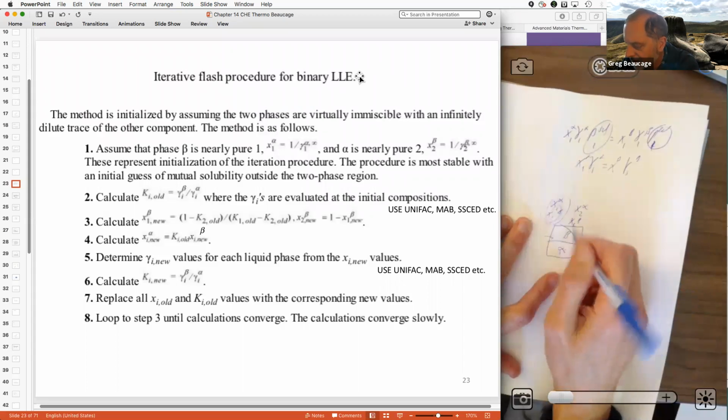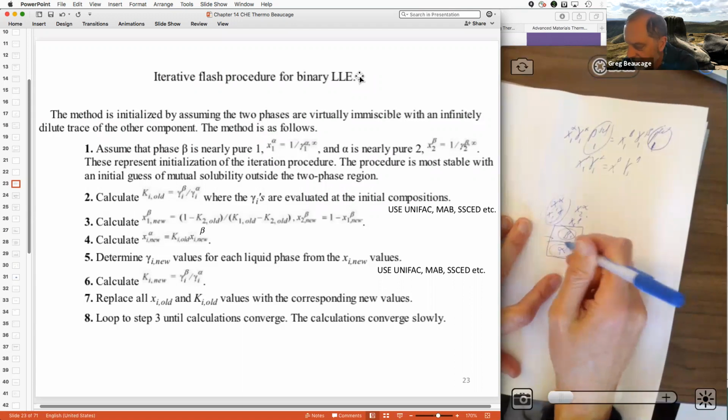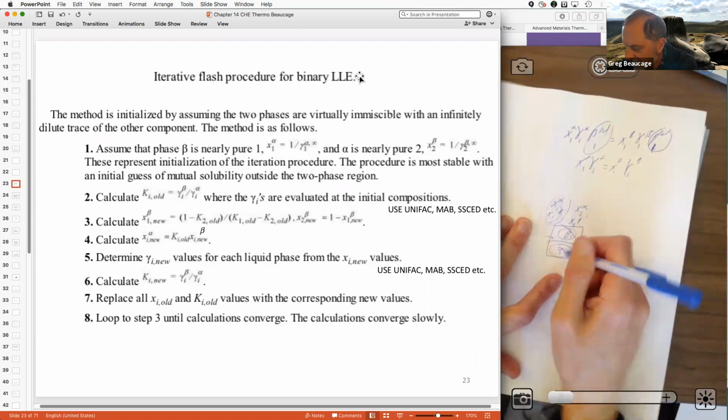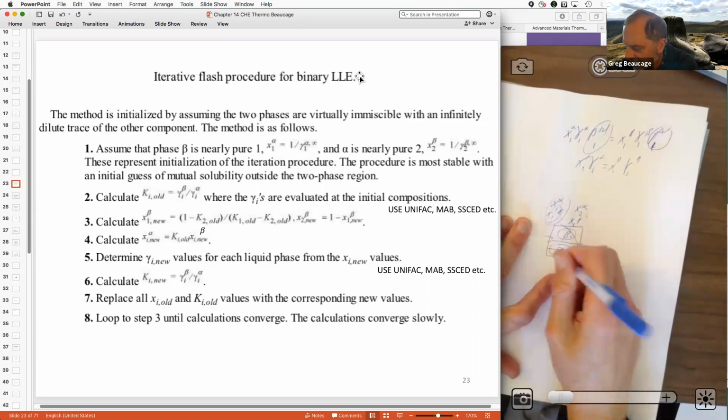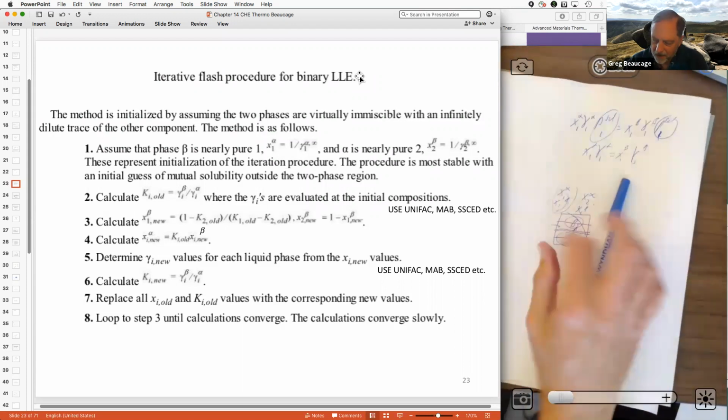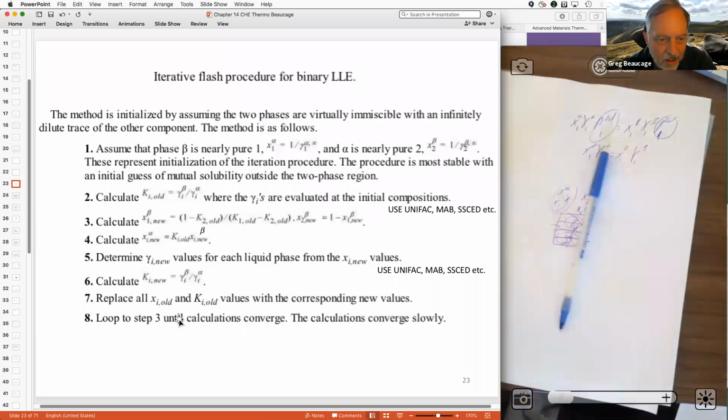You sum those two, you get the mass of alpha, you get the mass of beta, then you know how much alpha and beta volume they take up, or how it is split between the two phases. In other words, how much is the alpha phase, like 10%, or is it 50%, or is it 75%? Right. So you can tell the amount of the two phases from this by a mass balance.